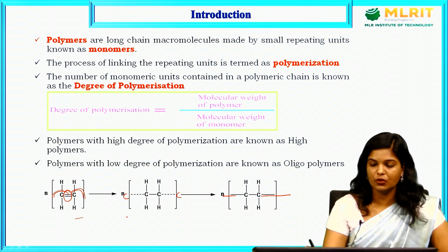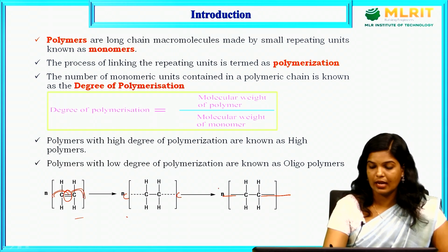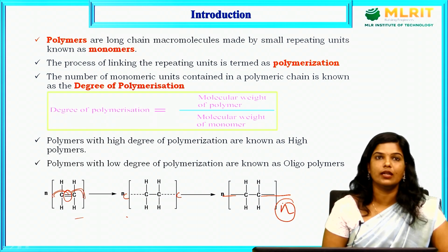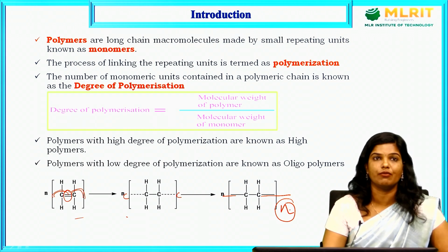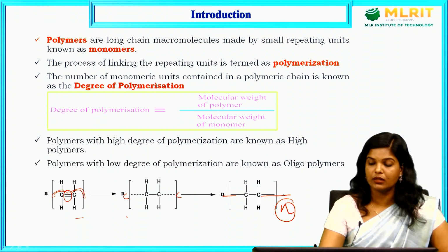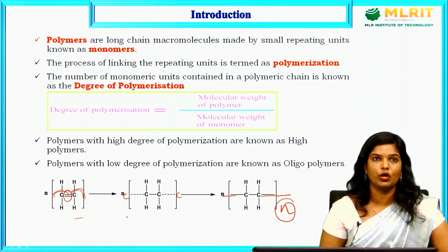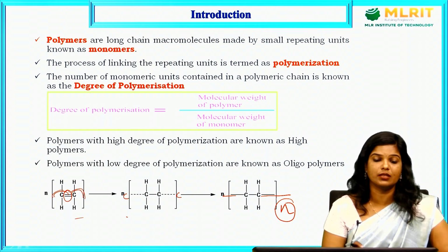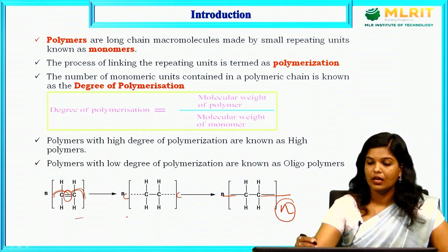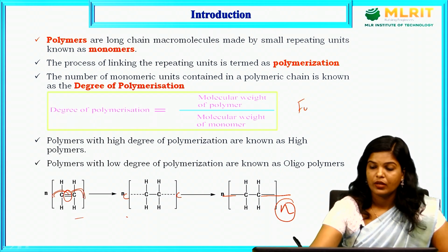This will be continuously moving, and it can be represented as N number of moles or by the term N, which is known as the degree of polymerization or the molecular weight. Whatever number we write for this defines the molecular weight of that particular polymer, or the degree of polymerization of that polymer. In one more term, we can say this is functionality. Now, what is functionality?